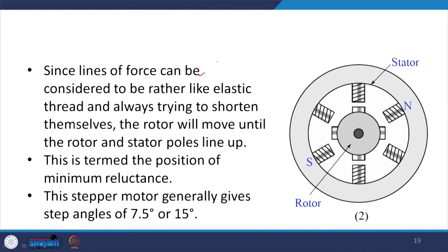So, it is basically something like the stretching of a thread. The lines of force can be considered to be rather like elastic thread, as I said, always trying to shorten themselves, and this way the rotor will move until the rotor and stator poles line up basically. So, that way we get the rotation of the rotor.